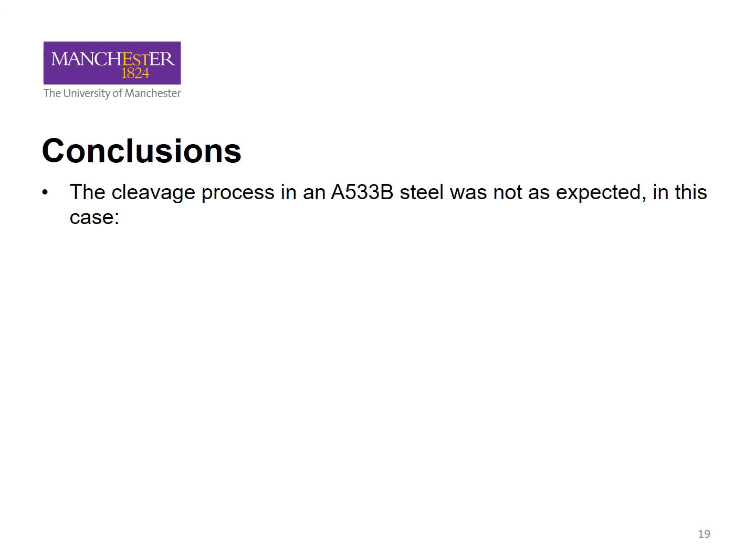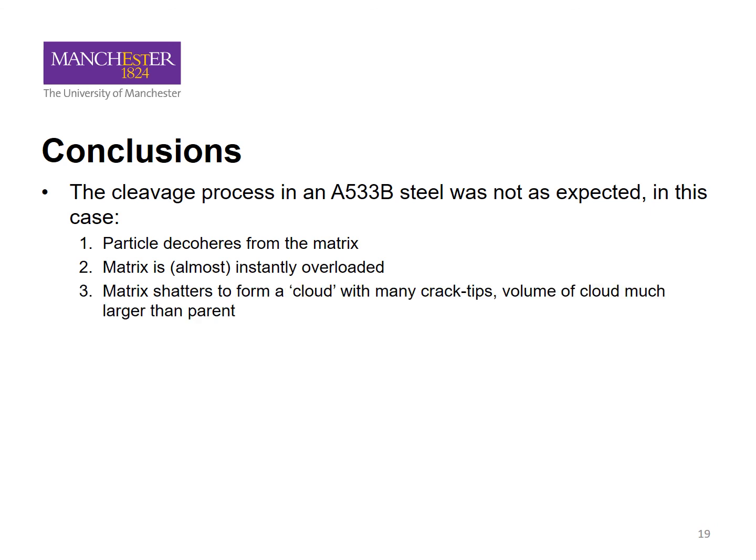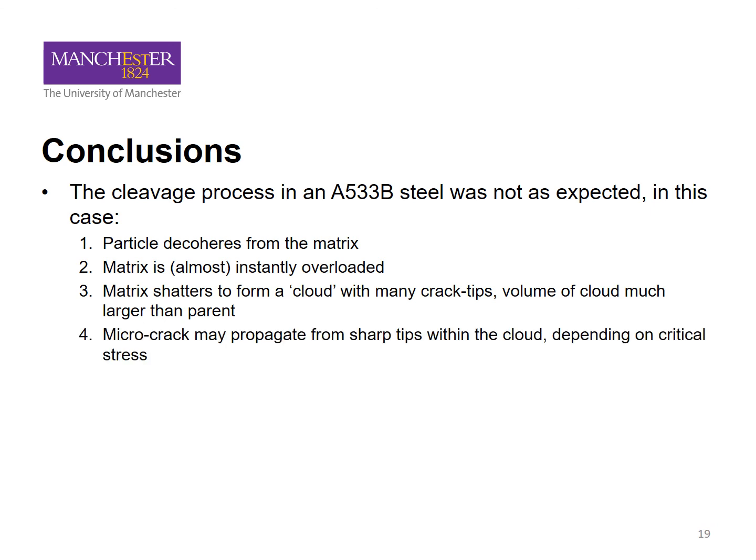In conclusion, the cleavage process in an A533B steel was observed and was not as expected. In this case, it appeared that the critical event was particle decoherence from the matrix, not particle cracking, as was expected. This leads to matrix overloading, which then shatters to form a cloud with many crack tips, and the size of the cloud is much larger than that of the particle. Microcracks may then propagate from the sharp tips within the clouds.